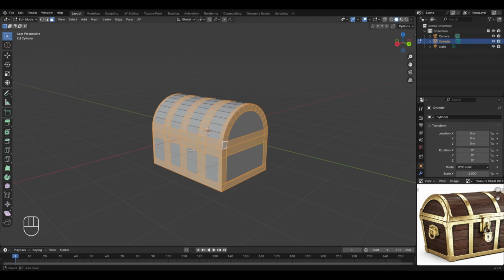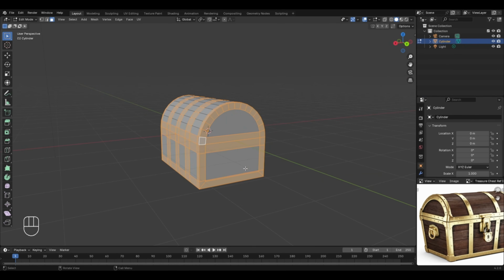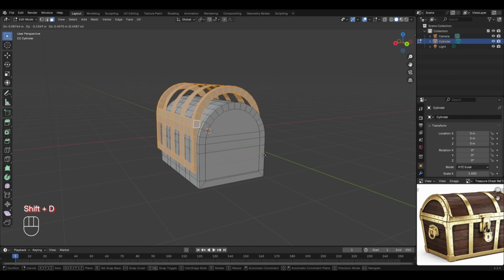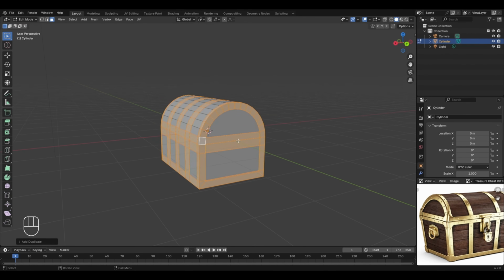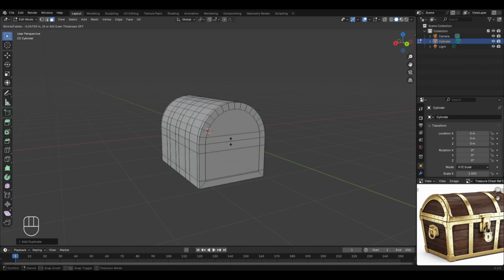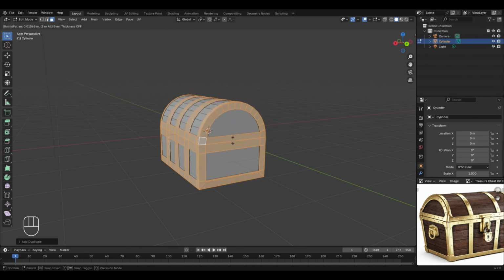Now to convert them into a metallic cage, we'll first create a duplicate of the selected faces. So press Shift plus D to create a duplicate, then right click to cancel the movement, and now to add some thickness, press Alt plus E for the extrude menu and select extrude faces along normals. Then if I move my cursor up, then you will notice that the selected faces will begin to extrude along their respective normals.